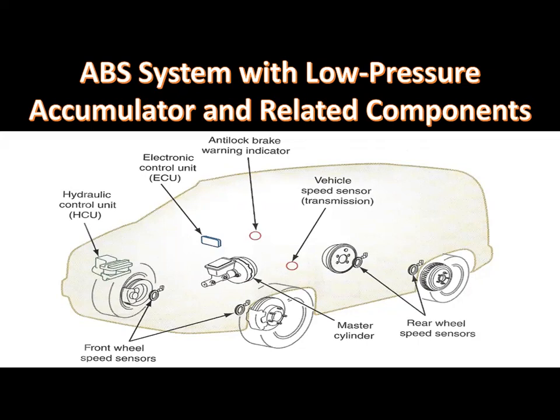If within a few milliseconds the wheel speed sensor still indicates that wheel lockup is about to occur, the module opens the normally closed solenoid and allows some brake fluid out of the brake caliper back into the master cylinder reservoir. This action reduces pressure in the caliper and prevents wheel lockup. The module pulses the solenoids on and off to maintain maximum braking force without allowing wheel lockup. When the module pulses the solenoids on and off during the anti-lock function, the driver may feel pedal pulsations.